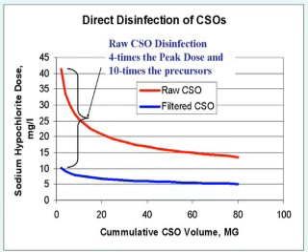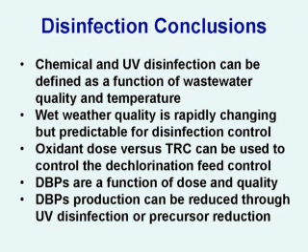Another thing the practitioner might look at is, what are we creating when we're putting these high doses in? Well, we're creating high total residual chlorine, and that high residual chlorine needs to be knocked down so we don't have toxic effluent and kill the aquatic life in the receiving water. So this plot shows a relationship between the dose normalized by COD and temperature versus the effluent TRC. You can see you have pretty high levels there, and you're going to have to dechlorinate, possibly according to a regression equation like this.